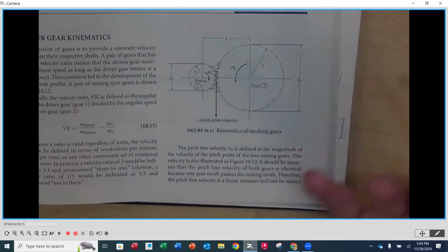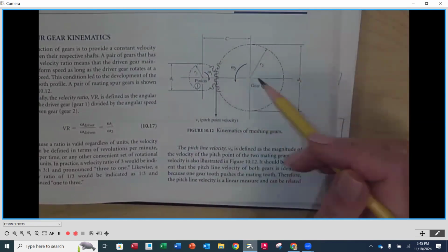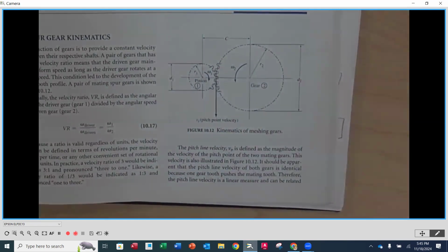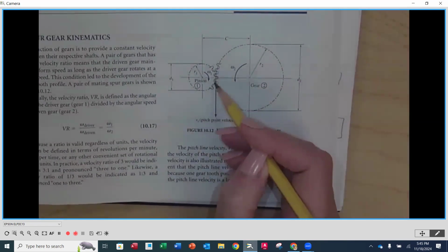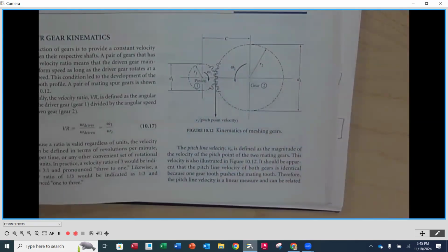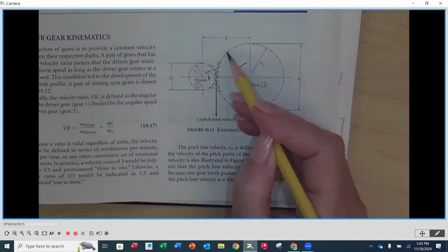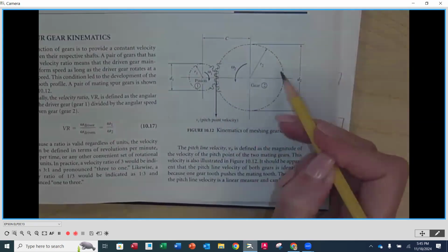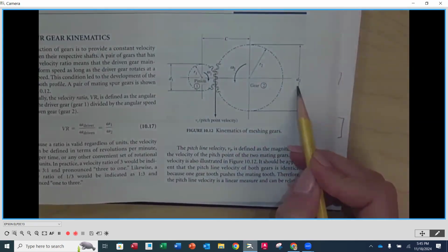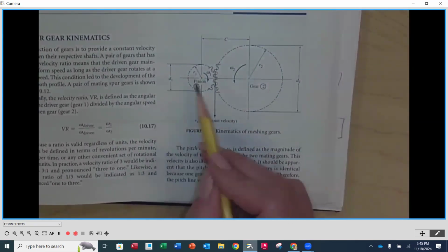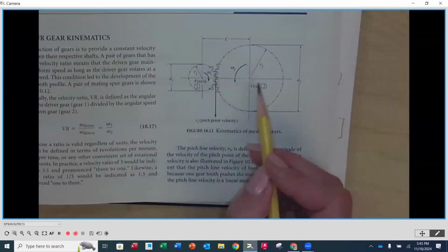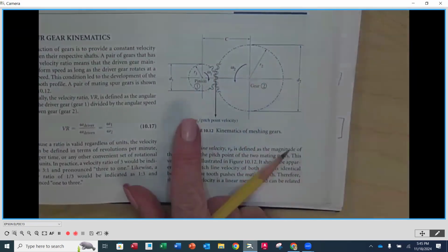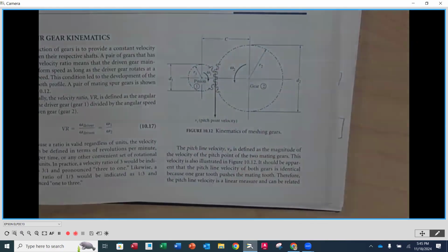What this shows, I think it's nice to see two full gears, and you can see where they're meshing with one another, where we have the teeth drawn. As we saw earlier, this circle right here would be the pitch diameter. Notice that this is diameter 2, this is diameter 1. So this would be the pitch diameter of the pinion and the pitch diameter of the gear. Pinion, again, is the smaller of the two gears that are in engagement, okay?